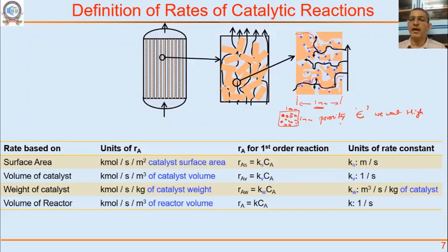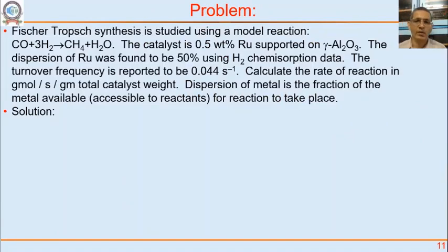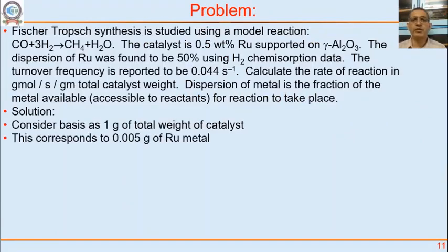So a lot of the catalyst is occupied by the pores, and we want tortuosity to be less. Then the diffusion will be fast, right? Tortuosity to be almost 1, right? But in practice, tortuosity is 2, 3, 4, 5. That high means that much more tortuous the path is.